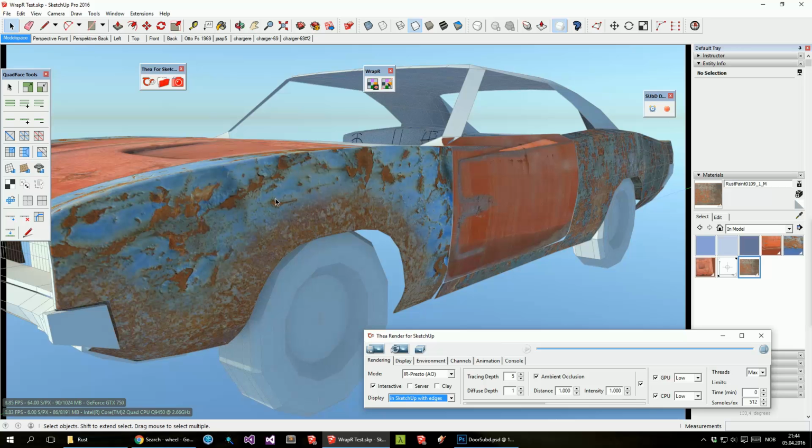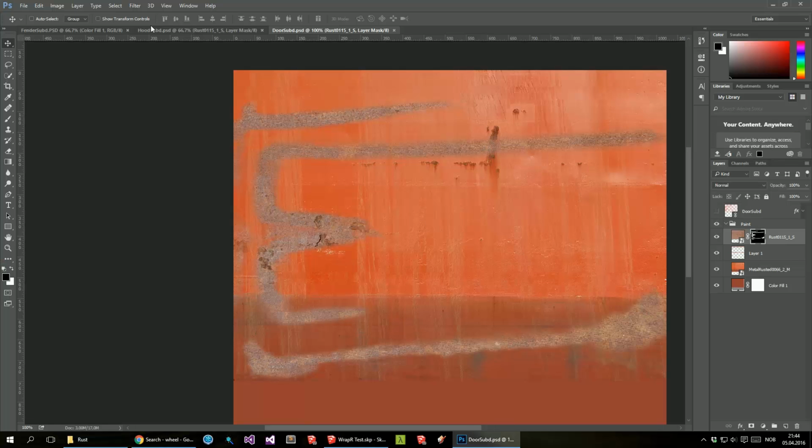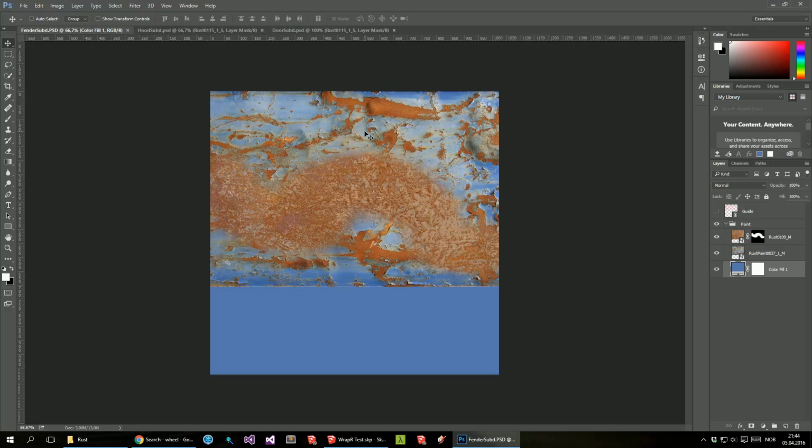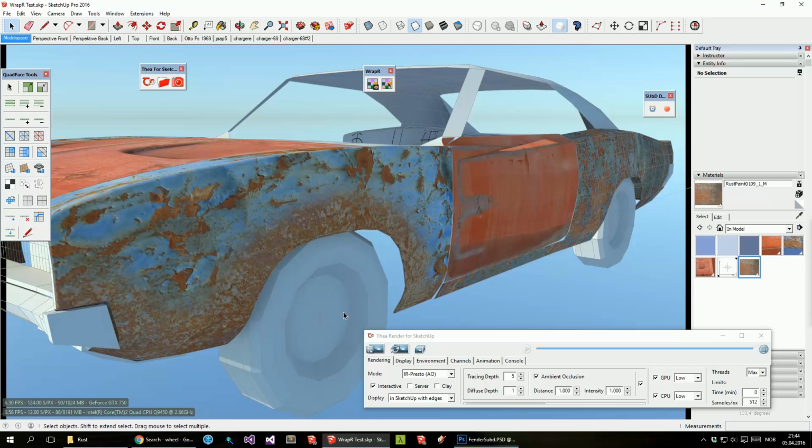Now, from that, this could go on and create a specular map from where all the metal paint is, using color select in Photoshop and extract all the blue pixels there, and from there add that as a specular layer into the rendering engine, so you get some reflection shininess onto that.